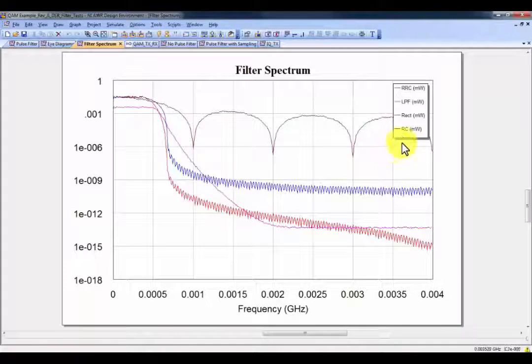We then have what we studied in lecture, a raised cosine filter, and that is this red filter here. You notice that it has a very tight bandwidth. The reason it does is because the cosine has an impulse response that looks like a sinc function. We know a sinc function in the time domain would give us a perfect rectangle in the frequency domain. So the raised cosine impulse response was basically generated to give us the sharpest filter we could get in the frequency domain. And then I also have here something called an RRC.